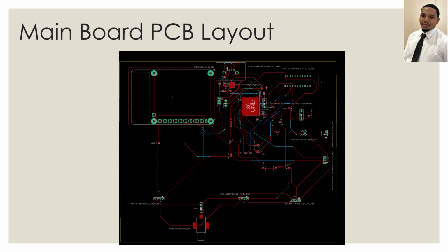To the right of the board is a blocking motor device and the laser, which will both be plugged into pin headers. The CCD is in the top right corner and is intentionally placed there so it will be the furthest from the voltage regulators in an attempt to avoid any noise emitted from the switching regulators.